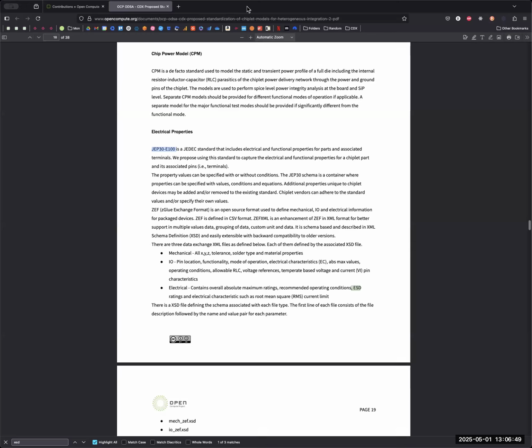I have spoken to many people in different summits on this topic in the past, including people selling the ionizers to the foundries. My takeaway has been that with the usage of ionizers, when you do the wafer to wafer hybrid bond, that's enough to consider a 0 volt CDM ESD-less environment essentially for the bonding process. That's for hybrid bond.